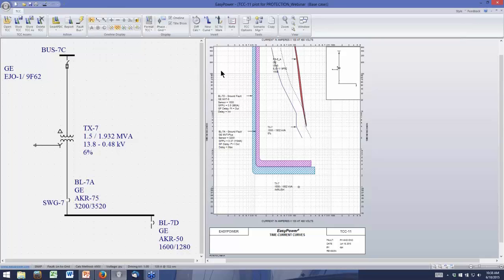Of course, the advantage of the ground fault protection is that it doesn't see normal load current. It'll see if you have some imbalance if you don't compensate for that. But in general, it doesn't see load current, so it can be more sensitive. The phase overcurrent devices have to be able to handle the full load amps so it doesn't trip on load current. So the advantage of ground fault is that it can be more sensitive.